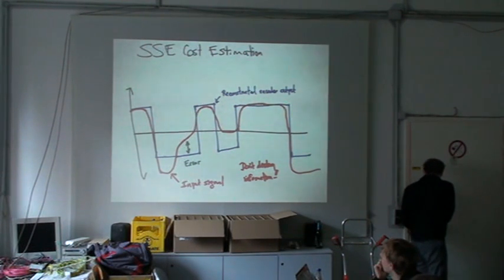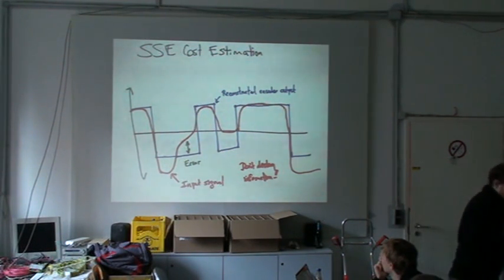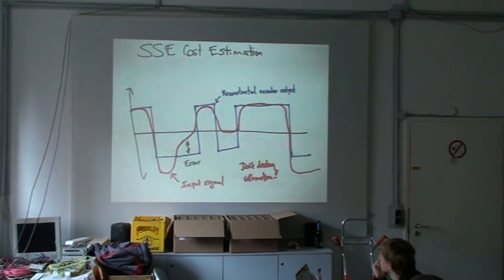So this is why, and this comes in OpenBTS in the implementation of encryption, what you have to do to make this work is simply invert the sense. You're basically going to do the equivalent of something like a sign inversion. When you're performing the decryption phase, the deciphering phase, you're just going to invert the sense of each of these soft symbol estimates. The reason you have to do that in GSM is because ciphering was an afterthought, and it's added at a very low level in the stack, at the point before you've actually finished recovering the signal.